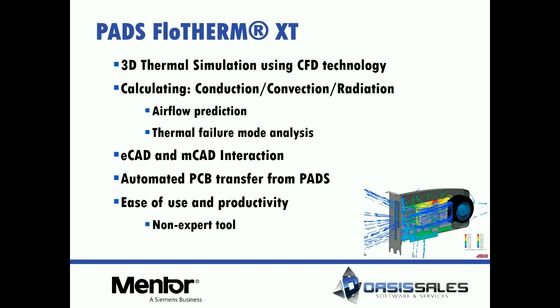So what is FloTHERM XT? Well, as I just kind of alluded to, it's a 3D thermal simulation software using CFD technology. It will allow you to solve for all three modes of heat transfer, including airflow patterns. It will allow you to read in ECAD data from PADS, combine that with MCAD data from, for instance, SolidWorks or Creo, put everything together in an assembly and understand how everything's going to work in terms of the heat transfer. So we're going to see some automated PCB transfer from PADS.